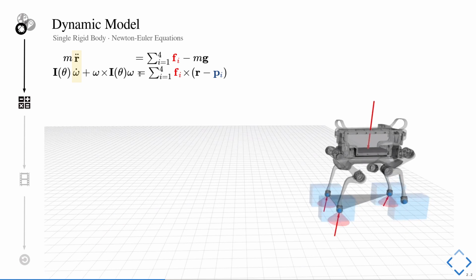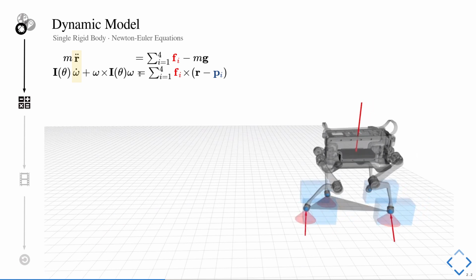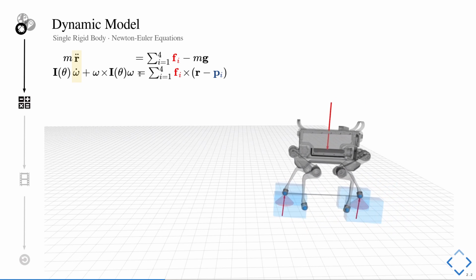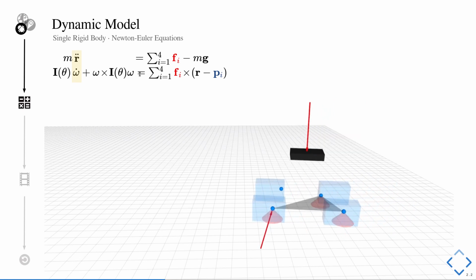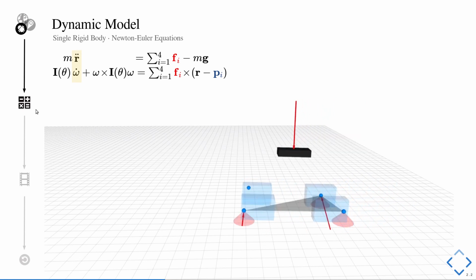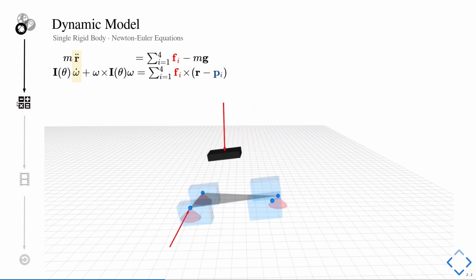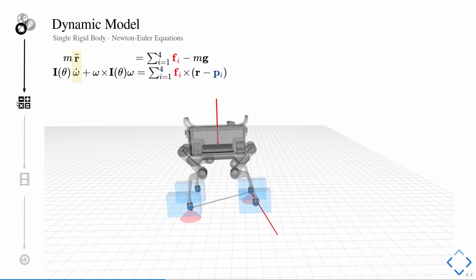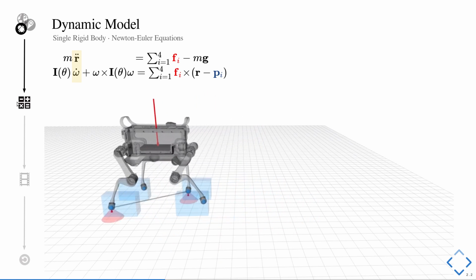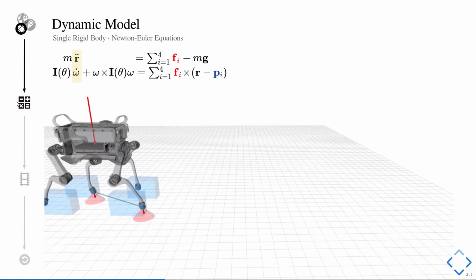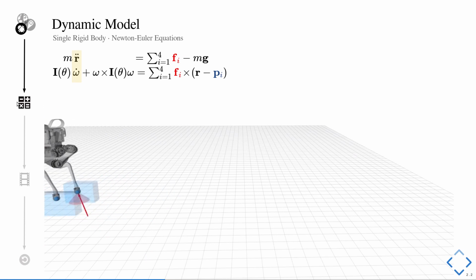When we look at how these produced motion plans look, at every point in this trajectory we're enforcing the above equations as equality constraints in our optimization problem. So while the optimization algorithm is choosing the foothold positions and the forces, at the same time it's making sure that the base motion it's choosing complies with the above equations.